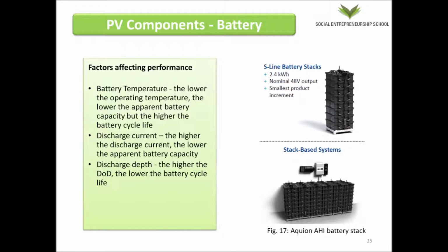Battery performance and life cycle are dependent on operational factors. The depth of discharge of a battery is a measure of the percentage of its capacity that has been used up. For instance, lead-acid batteries are typically discharged to 50% of their total capacity. The daily charge-discharge cycle of the battery can also be a factor in its performance. Lead-acid batteries, for instance, have a reduction in their capacity if left partially charged for extended periods of time, and therefore need to be regularly topped up.